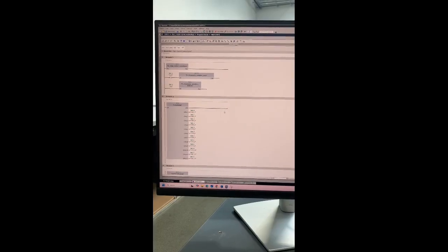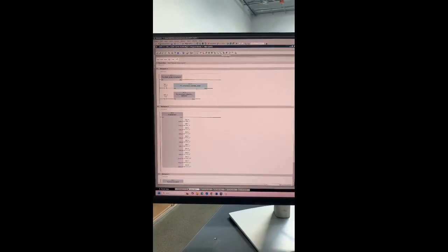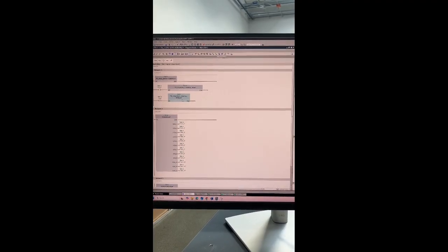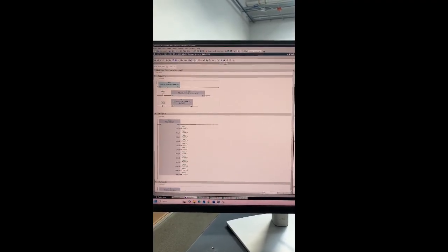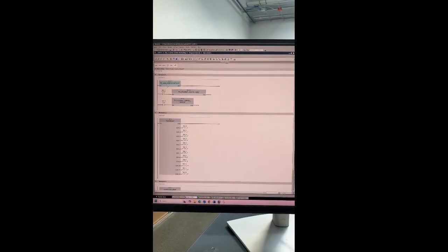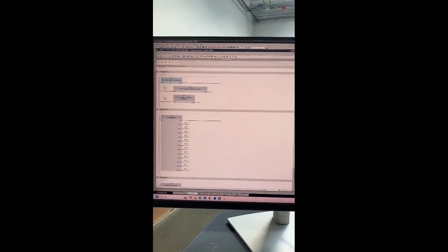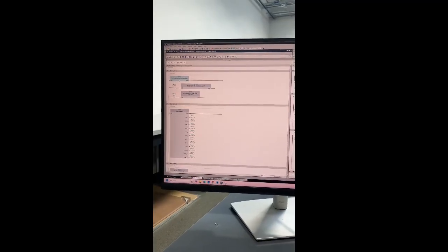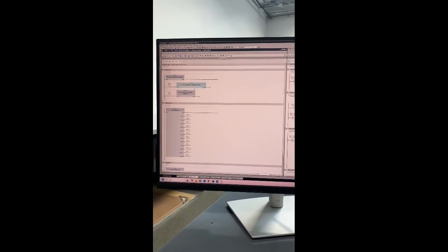Today we're working on lab 4, which is the implementation of sequence control for our auto and manual modes. I have a function call block for auto and a call block for manual as well. And then I also have a block for our FC edge detection, which requires the positive signal of the start button being pressed.